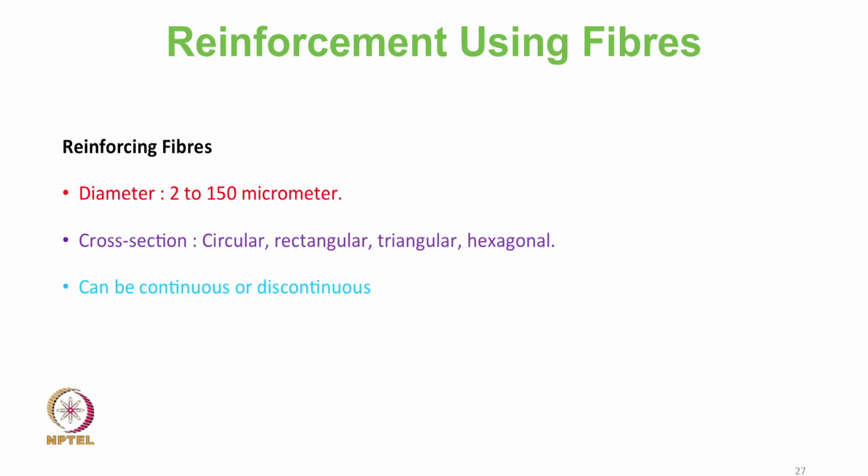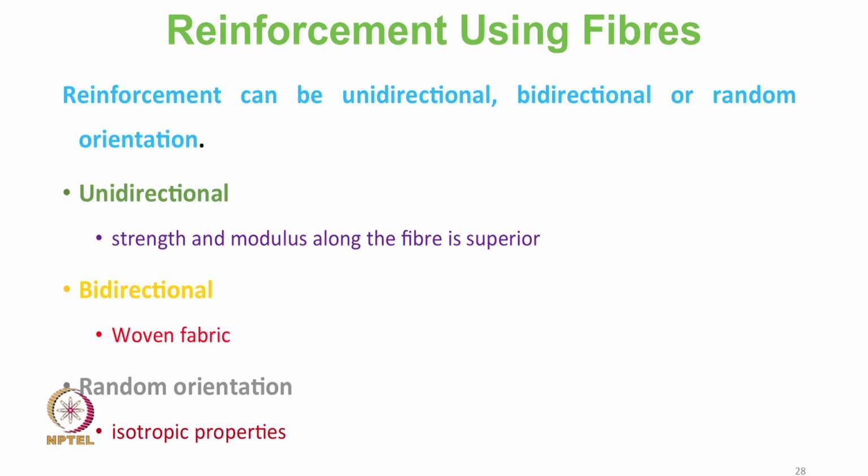And the continuous fibers, that is filaments, are long, and in theory they offer a continuous path by which load can be carried by the composite material. In discontinuous fibers, the load is carried by the discontinuous fiber and shared by the matrix, transmitted to the other fiber, short fiber.